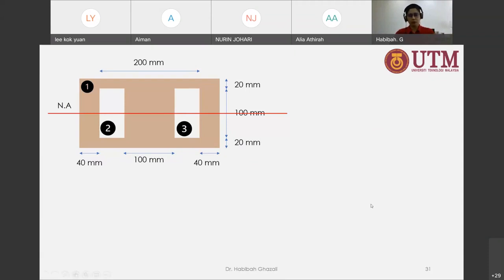I divided it into three shapes, which are the large rectangle and these two small rectangles. Those two small rectangles sit at that location of the beam next to the original shape of the core material. So that is going to be drilled out. And this is symmetric, so we know that this is going to have a neutral axis located at 100. This is 100, 50, it's another 2.